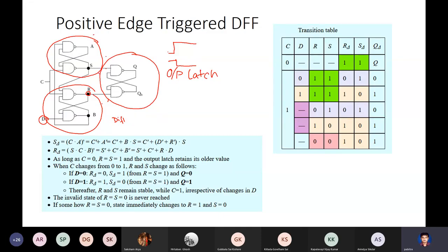And because of this set reset mechanism, this top latch tries to set it in this part, the bottom latch tries to reset it in the same part. So the only time span where both set and reset agree with each other is at the edge. Okay, I'll come to the detail. You can think of it like this: the top latch tries to set this output latch here in the on part of the clock.